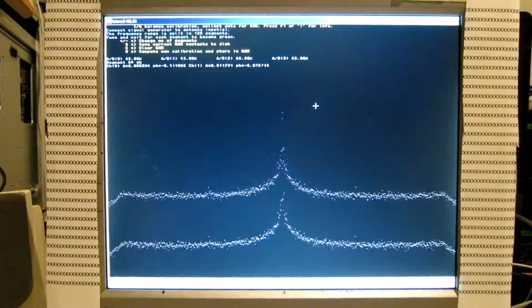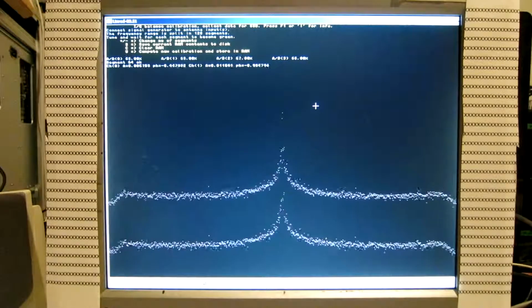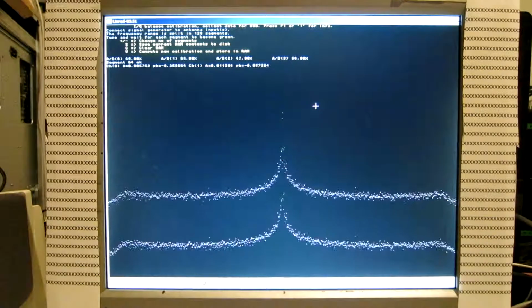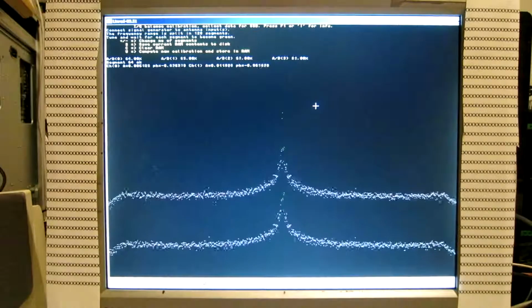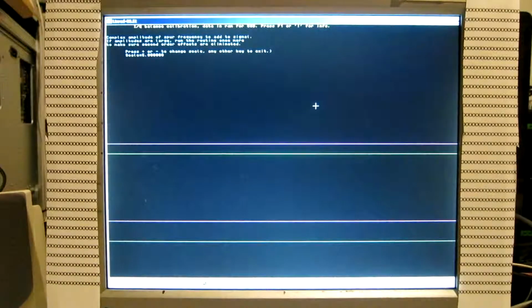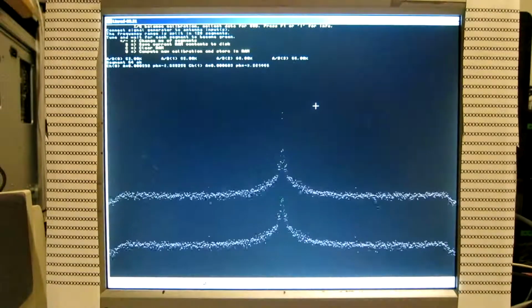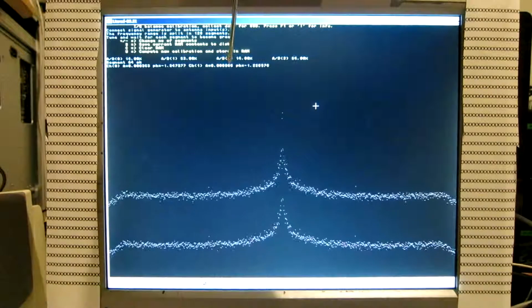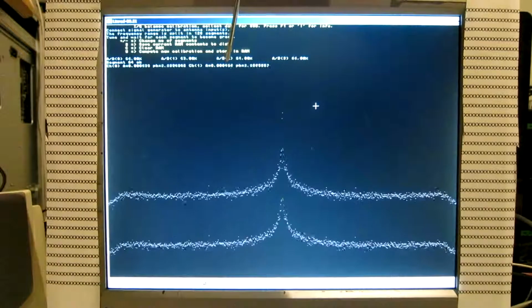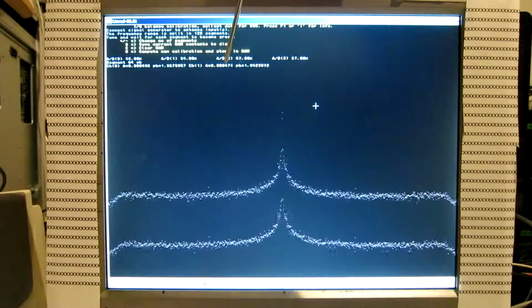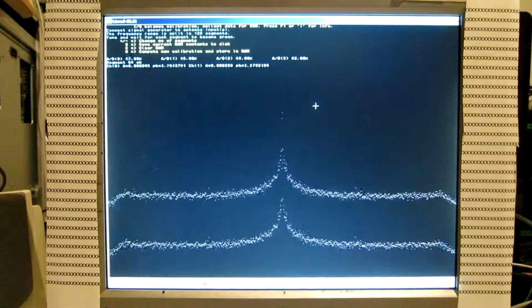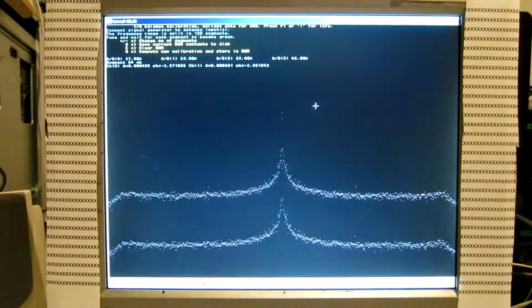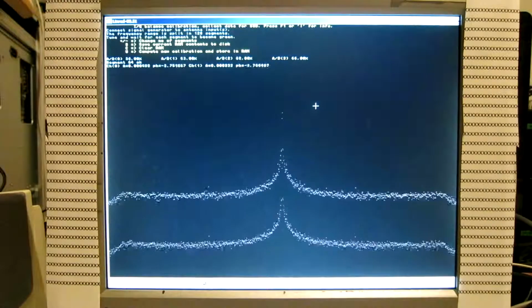Something like that. I can verify that this works by computing the mirror rejection just from one segment. That is U. And you see it now is flat. It will apply the same over the whole frequency range. Enter. And we can see here the amplitude of the mirror image is 0.003. And you can see it varies a lot. It's down in the noise. We have the sideband noise from the generator. We can do better than this by increasing the number of points in the FFT. That will, on the other hand, make the process a little bit slower.